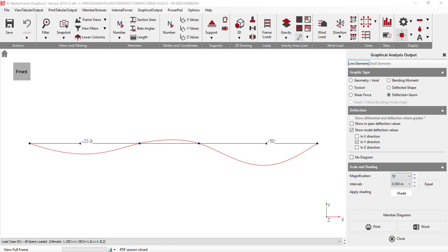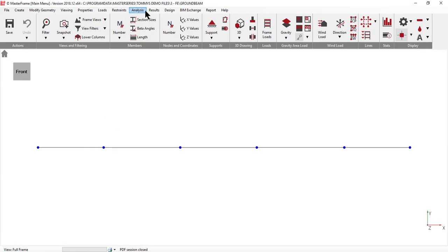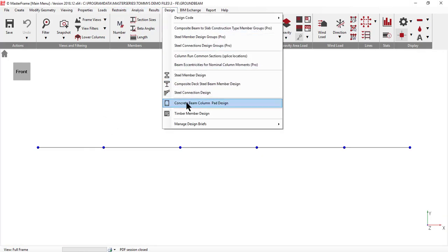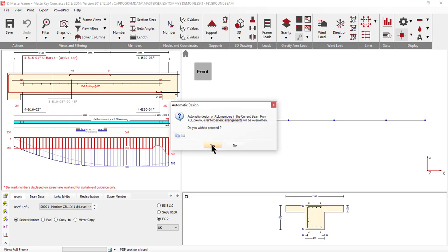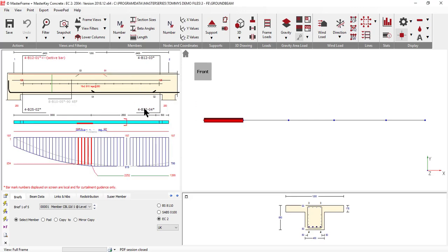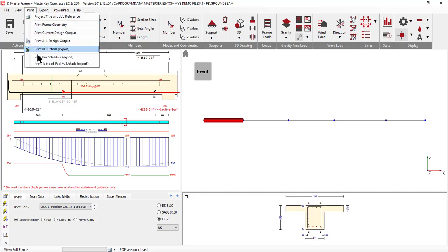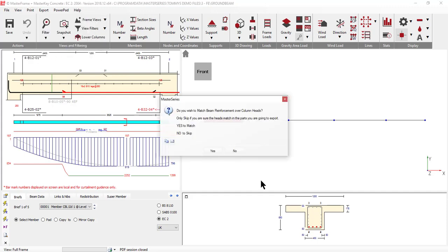Where does the bar bending schedule come from? The bar bending schedule comes from the program, without being rude. The frame analysis program in concrete design has the option, and obviously with our new settlements we're getting new problems. Let's just redesign all this. You'll see we need bigger bars here because of this settlement, so I'm going to stretch these bars a bit further, and now it's satisfactory. So export and schedule, and there you go.